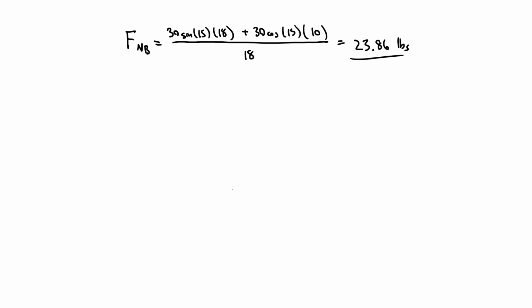I can also, at this point, go to the x equation. The friction force FF is going to be equal to 30 sine of 15, and so the friction force is going to be 7.76 pounds.